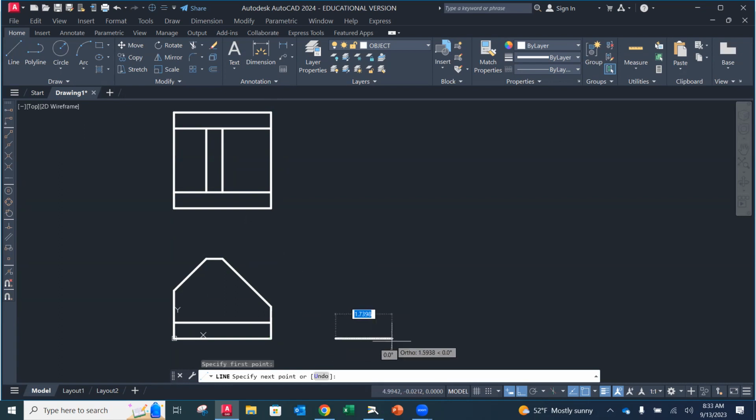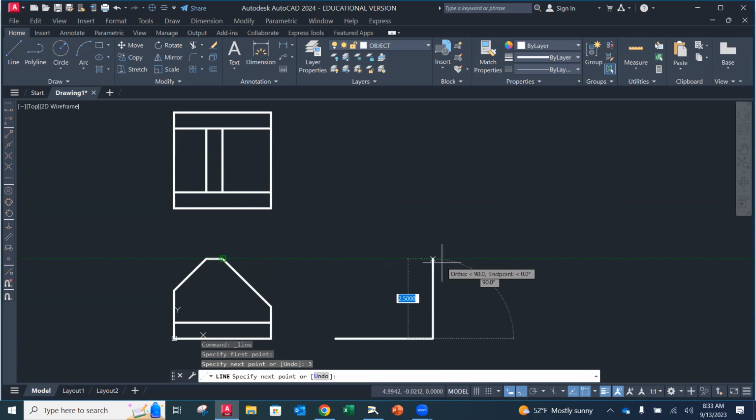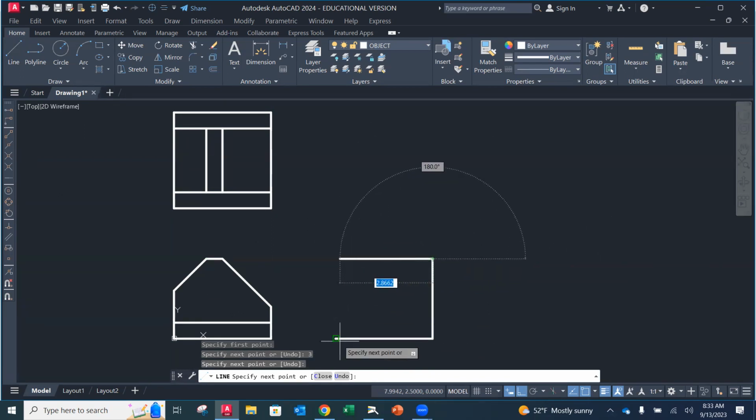I'm just going to go over here. My width is going to be 3 inches. My height, we know what that height is. I think it's 2 plus a half. We could key in 2.5, or you can activate the line over here, and it's going to snap to that height, and ensure that you're in orthographic projection. And I'm going to go over here and over here. I know I'm going to be trimming some of this off. Then I'm going to go in a 1/2 inch on either side.